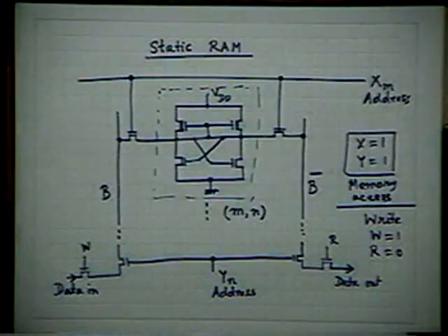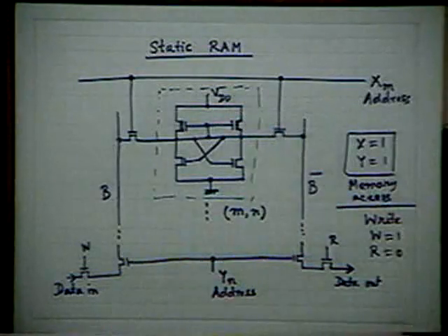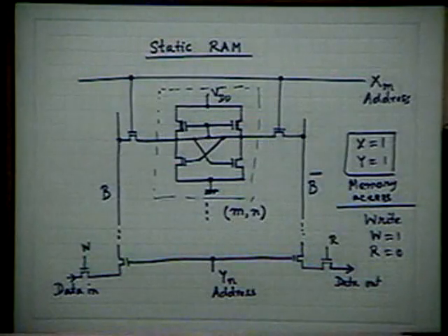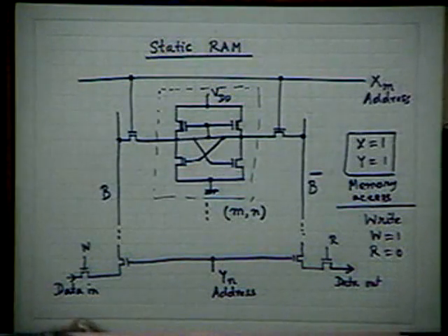And that happens. So even with this particular thing, whatever I have discussed, if I want to operate at a high speed, then I will definitely encounter problems because of the bit lines. In fact, the individual memory element is so small, extremely small, that its charging and discharging time may be very fast.